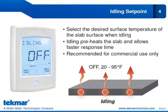We did discuss idling earlier in the training series, and we looked at idling and how we can use it to maintain a certain snow-free area ratio. So this would be operating our snow-melt system to maintain a minimum temperature during the entire snow-melt season. And the applications for doing so would be more commercial applications. Typically you wouldn't use idling in a residential application because it will increase dramatically your energy usage.